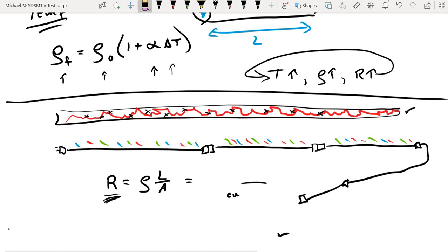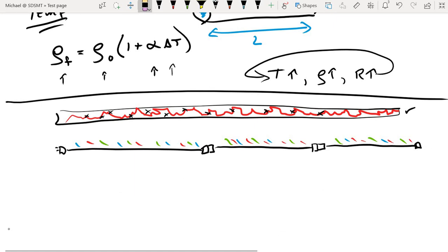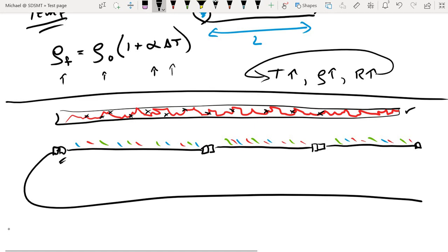Another case to consider is, well, maybe you follow the rules. Maybe you only connect 3 of these things together in a straight line, but now you have to plug the lights in somehow. And maybe you're nowhere near an outlet. So what do you do? You grab an extension cord, right? And you plug that extension cord in. Well, what did you just do by applying the extension cord? You introduced more length to the path, and this is going to cause the resistance to go up again.